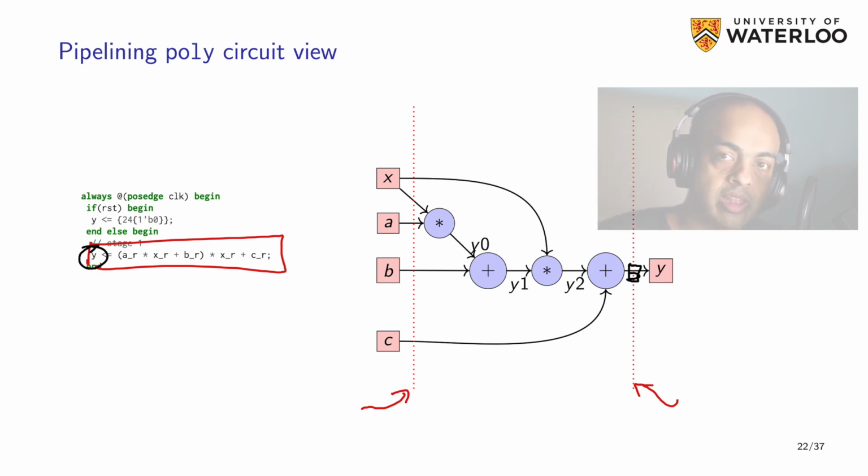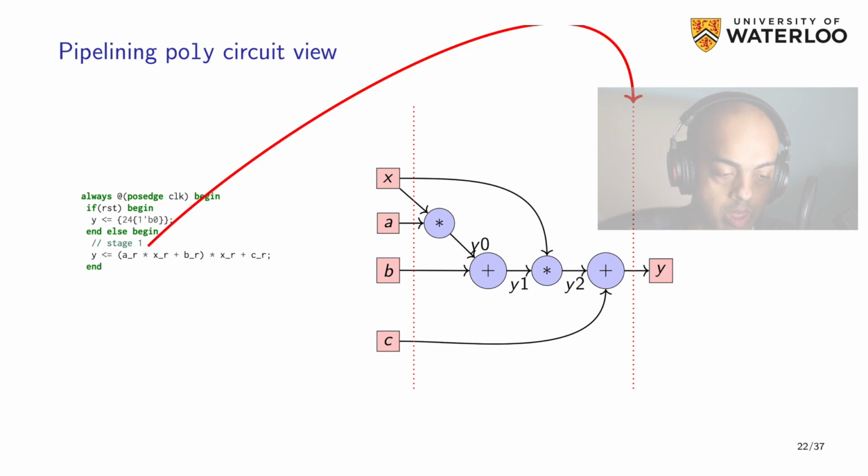The only tricky thing here is you need to ensure that you are pipelining signals to the correct depth before you consume them, right? So the X, B, and C signals have to be pipelined accordingly to varying depths depending on how deep your pipelines are, and then you have to use them at the correct moment in time, right? You can't just go back to B or inputs and just pick those directly without pipelining them accordingly. Okay, hopefully this was relatively clear.